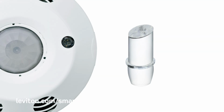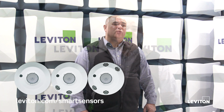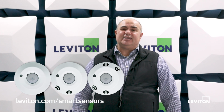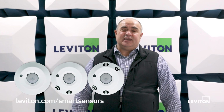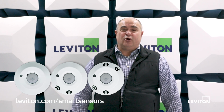The way that angled light pipe works is you can actually put it in as you mount the sensor in the middle of the room, and then turn the angled portion of the light pipe so it actually looks down into the daylighting zone. Now, this will allow you to properly measure the daylighting, natural light that's coming into the space when the sensor is not mounted directly in that particular part of the room.